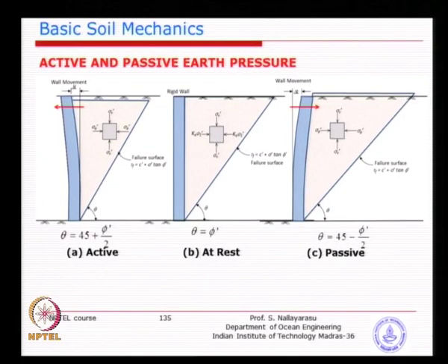Imagine if you go to this picture, I just go back again, if you have sufficient amount of vertical stress at the top. For example, you put so many concrete blocks, what will happen? The soil will not be able to heave upwards. So that is why in this case the effort required to move the wall is more than the weight of the soil, which is basically from this point to this point applied there. Then only the soil will move.